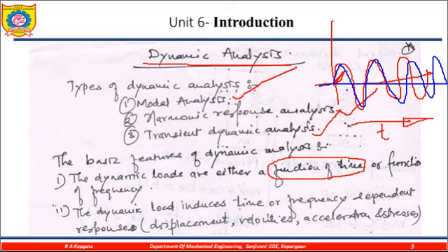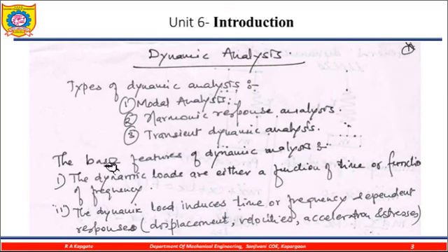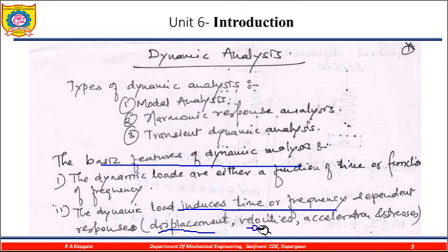In a nutshell, what are the basic features of dynamic analysis? The first is that dynamic loads are either a function of time or a function of frequency. The second is that the dynamic load induces time or frequency dependent responses. That means the dynamic load induces responses, such as displacements, velocities, accelerations or stresses developed in that component.